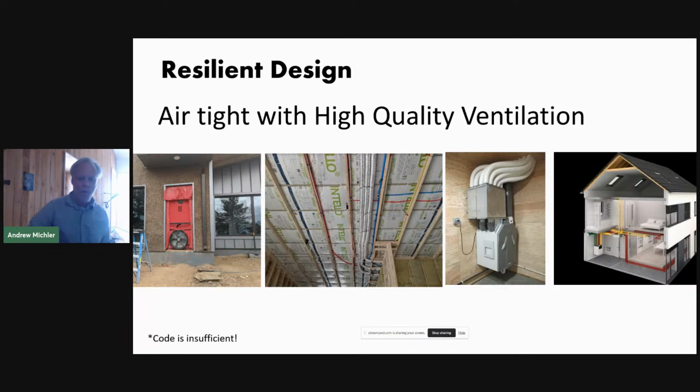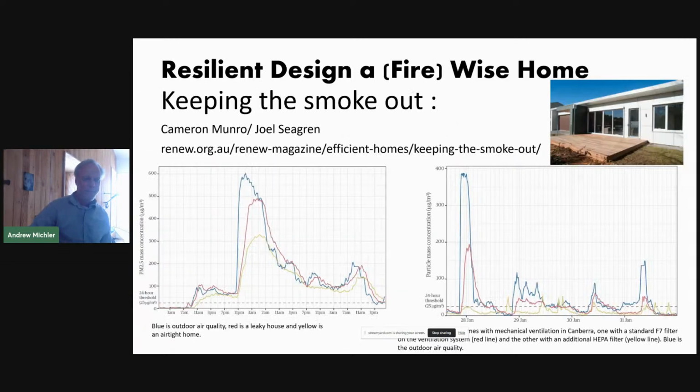And then, of course, we put dedicated ventilation systems into those buildings so that in the long term, people still have great air. Your building doesn't breathe, you breathe. So sometimes that idea of a building breathing is actually kind of the opposite of what we really want for a building to last a long time. We want a building that's dry and warm and doesn't constantly have air flowing through the fabric system to degrade it.